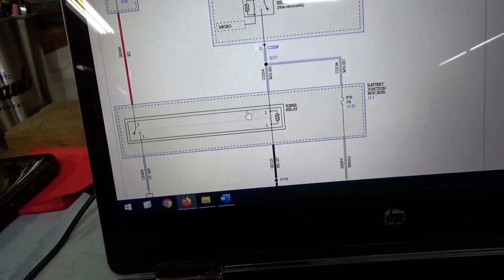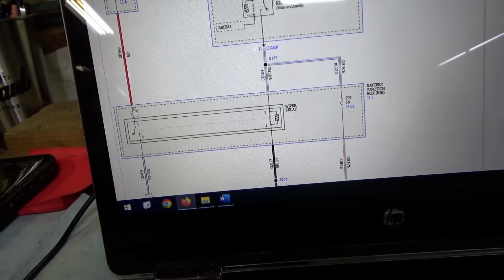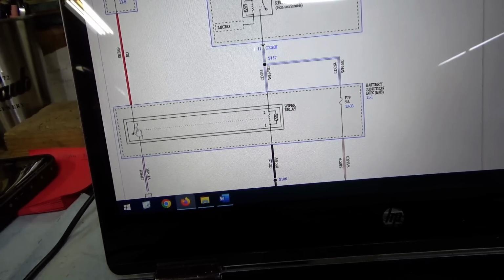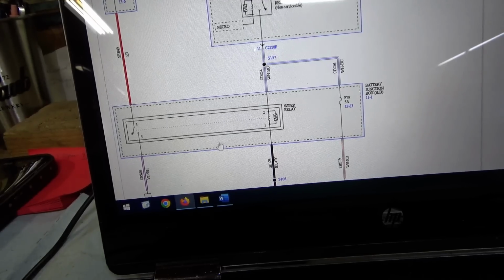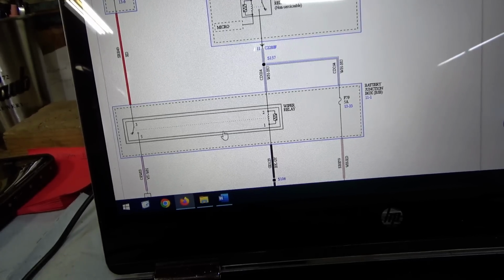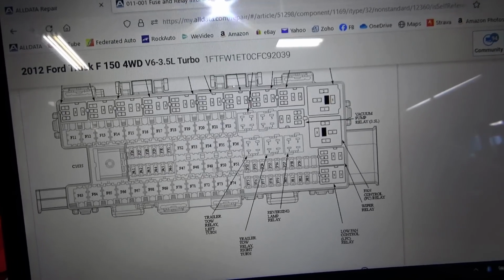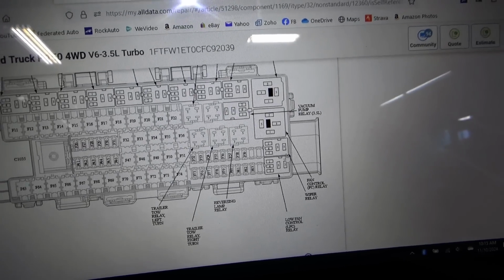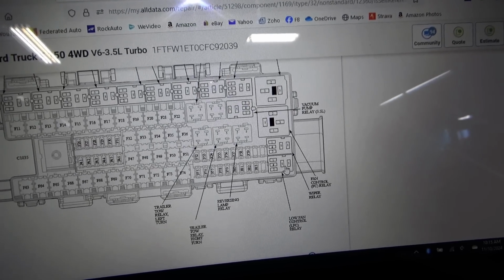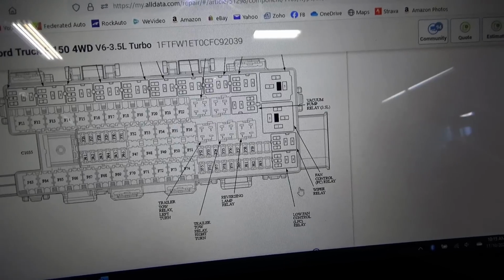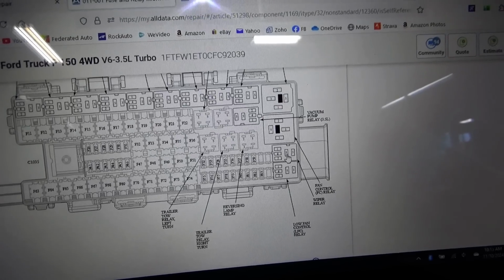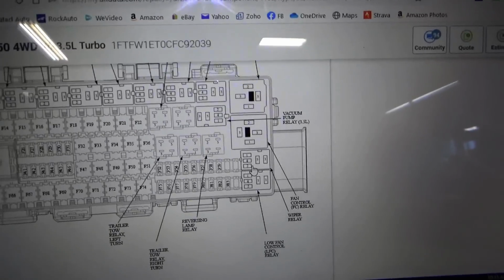Let's see where the wiper relay lives. We can at least see if the power is making it to here. We can jump these two if this thing is accessible. I don't know if it is, and we'll go from there. Alright, so here's our junction box. Fuse 49 looks fine. Wiper relay is the second one, lower right corner, right next to the low fan control relay. And I think the owner said he tried a new relay, but it didn't change anything.